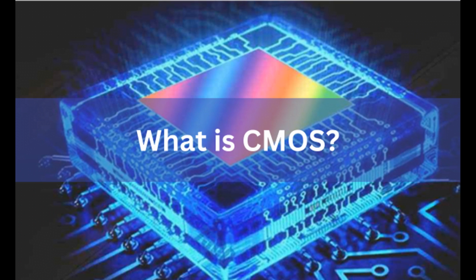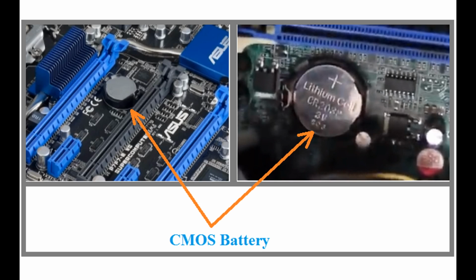Metal layers. Metal layers are used to create interconnections between different components of the integrated circuit. They provide the pathways for electrical signals to travel between transistors, resistors, and other components. In a CMOS integrated circuit, you'll find both N-type MOSFETs, NMOS, and P-type MOSFETs, PMOS, arranged in a complementary manner. NMOS transistors are used to pull the output down to ground, logic 0, while PMOS transistors are used to pull the output up to the supply voltage, logic 1. By combining these two types of transistors, CMOS circuits can perform various logical functions efficiently while minimizing power consumption.